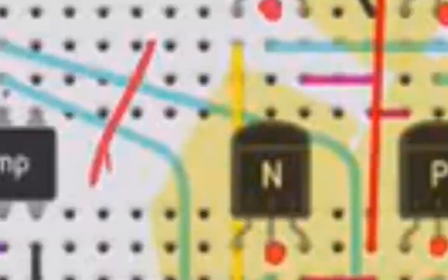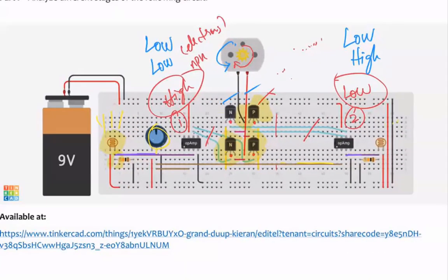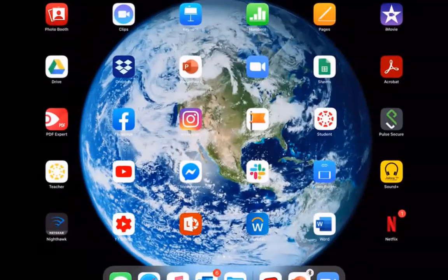Will there be any current? Yes, folks. No current, because the transistors will be off, no current flowing through the motor. And similarly, if both our comparators are high, again, the difference will be zero, transistors will be off, and nothing will go into the motor, so it will just stay idle.